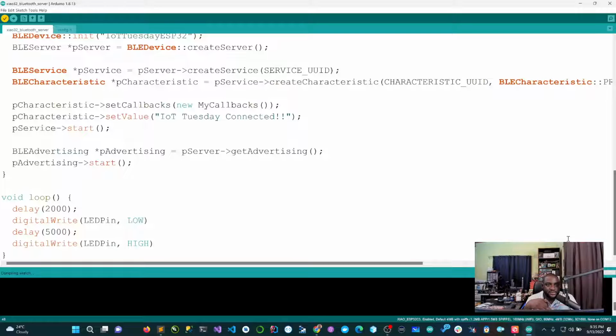It's just to show you how to do it. But if you're going to deploy on a device for production use, you need to consider sleep and wake times, so that you don't exhaust the battery on the XIAO. Because if you keep doing this, you're going to kill it. That's something we can talk about at another time.